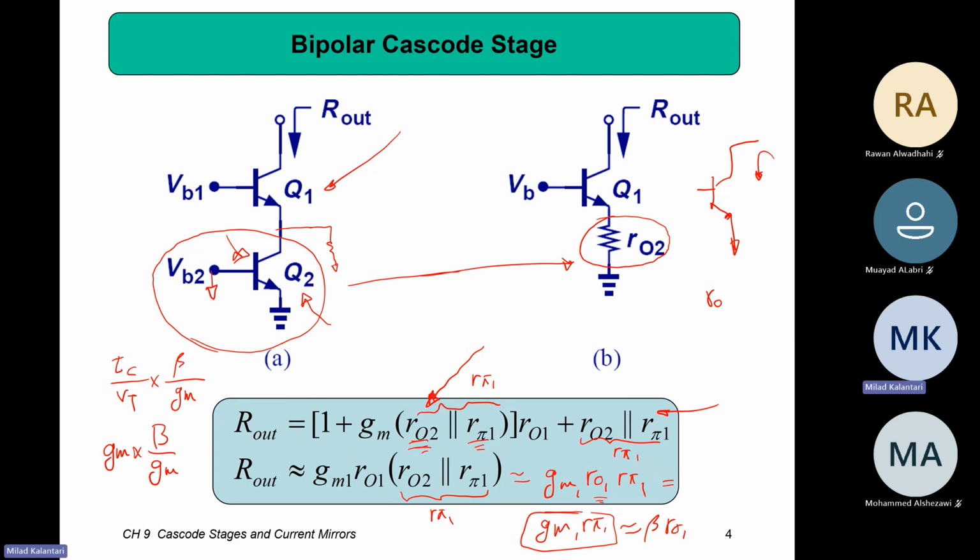With this config, we call it the cascode, having two stacked devices on top of each other. So what we are seeing is stacking up the two devices and looking at the collector of the top device, the impedance is beta times higher than normal, right?